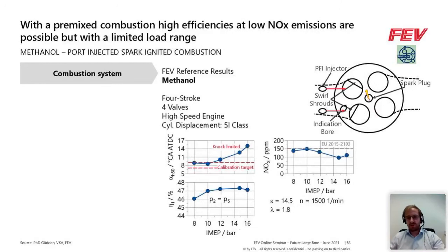And last but not least, we have also investigated premixed methanol combustion. Here you can see an example from our high-speed single-cylinder engine testing. And here we've tested with a quite high compression ratio to basically see if operation of a premixed methanol engine with large bore diameter is possible.